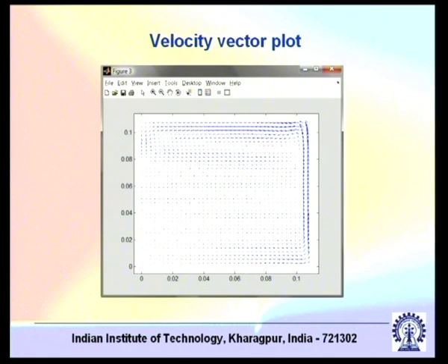you can use. So for example, this is a plot shown using MATLAB as a GUI interface. What you are doing here is using a MATLAB inbuilt function called quiver. If you have u and v as two velocity components, quiver u comma v generates the velocity vector plots in MATLAB. This is just a generic example, but you can use different types of graphical user interface. For contour plots in MATLAB you can use a similar function called contour.